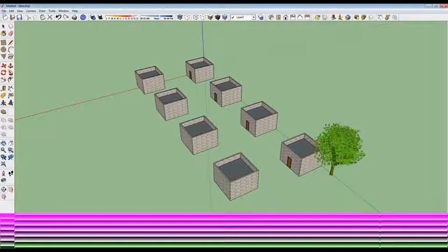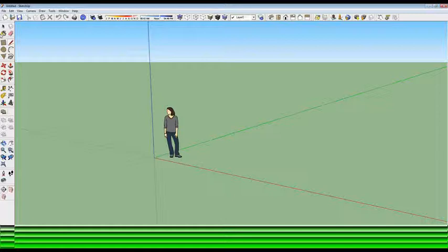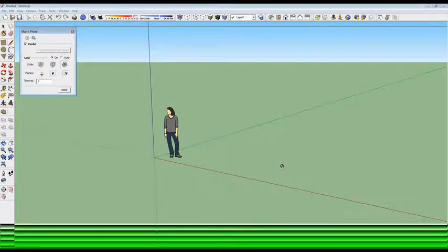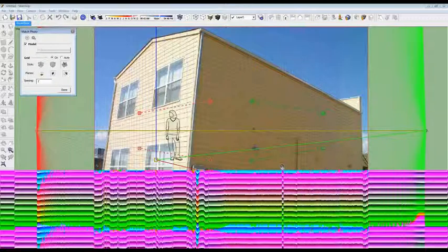So along with drawing and building things on your own, you can actually also use the photo matching, which is a great tool that most people are very familiar with at this point. But we can go ahead and take this photo mapping, and this is just a generic house, and specify the orientation of the actual points of the image as well. So we can take these lines here, and you just essentially move them around, and then you essentially make them match the orientation of your photo.